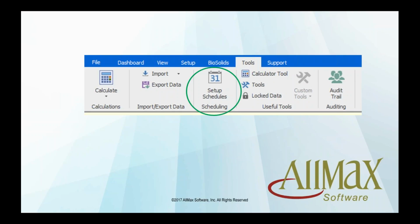Now, one of the things I usually suggest here on the schedules, and it makes it a little bit easier, is that if you're doing a client server, say you have a network and your database resides on a server, we recommend that these schedules be set up on that server. The reason being is that the client PCs may get shut off at night. Well, the server is usually running all the time. And by doing it on that, it's not worrying about that network resource to go and calculate that information.